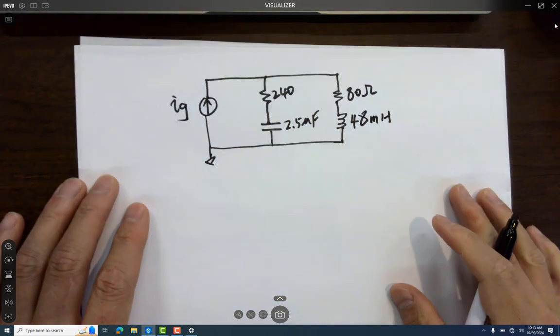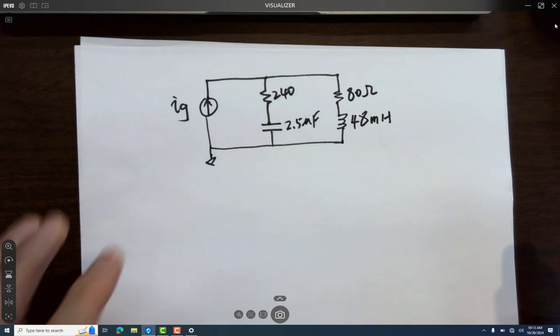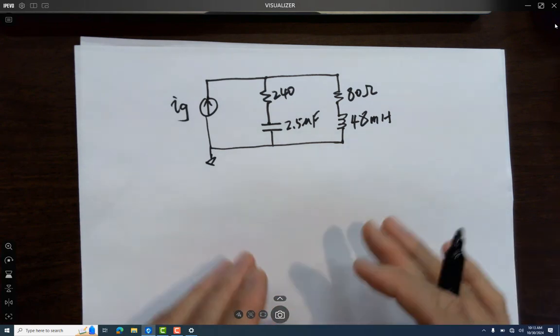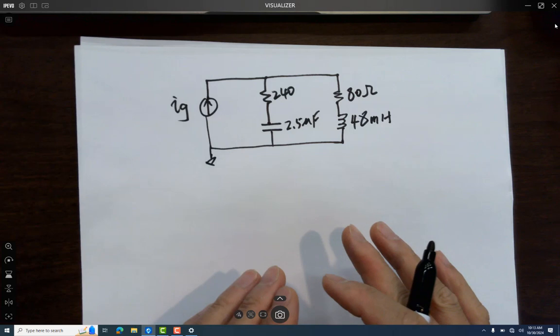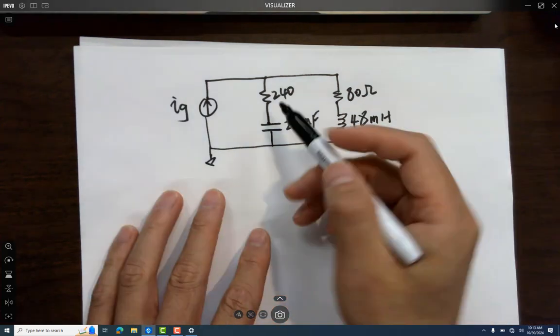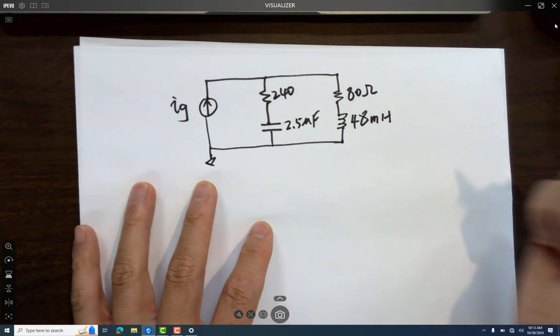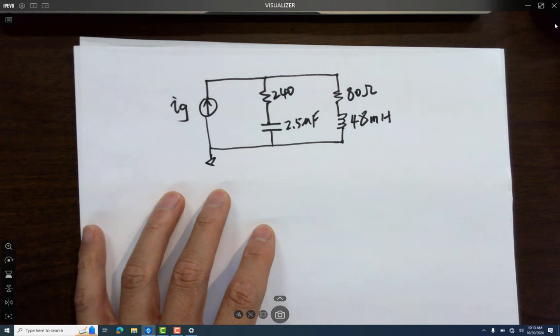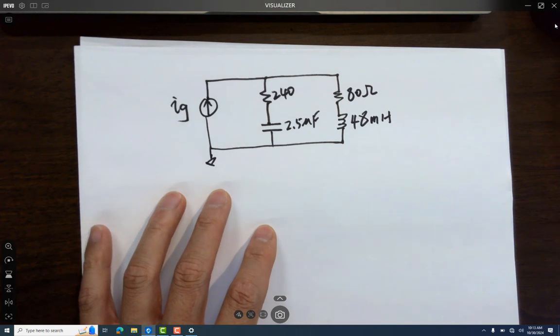So first thing, it's Ohm's law, KCL, KVL, mesh, node, parallel resistor, series resistor, all these rules apply to this. Good news. The first step is just to convert into impedance. Impedance for capacitors and inductors just introduces a frequency component into the resistance, but it's called impedance. Eventually, you just use it as a resistor.